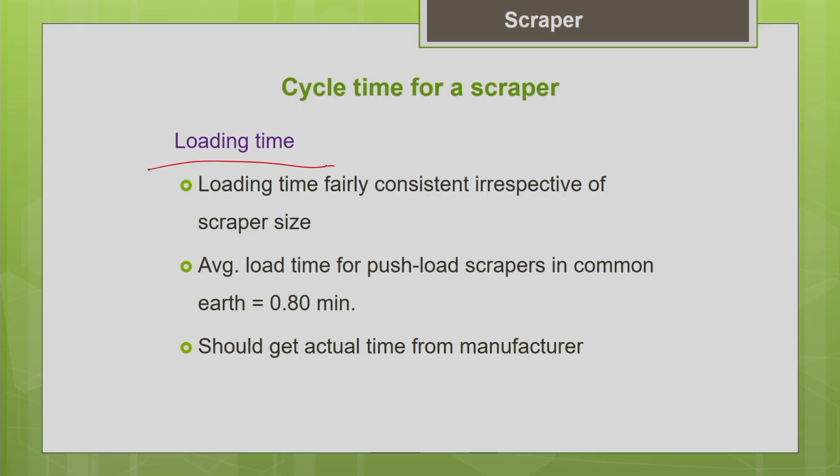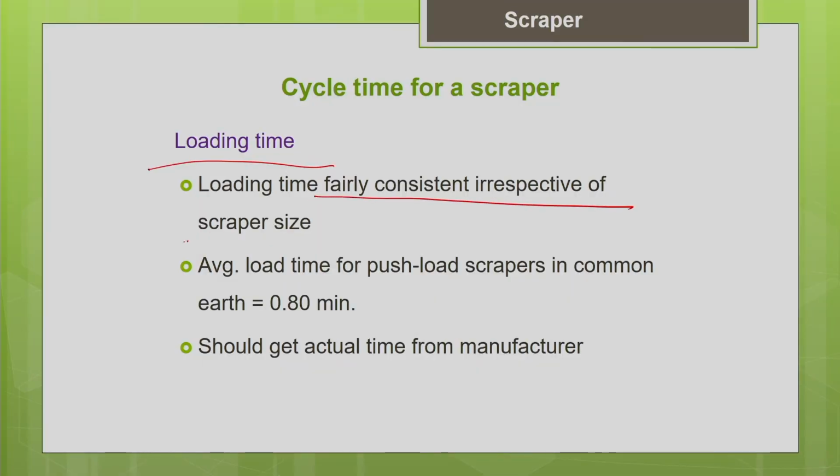Now, let us see what the loading time is. Basically the loading time of the scraper is fairly consistent irrespective of the scraper size, whether it is a smaller scraper or a bigger scraper. In both cases, commonly we assist the scraper with the help of a pusher.